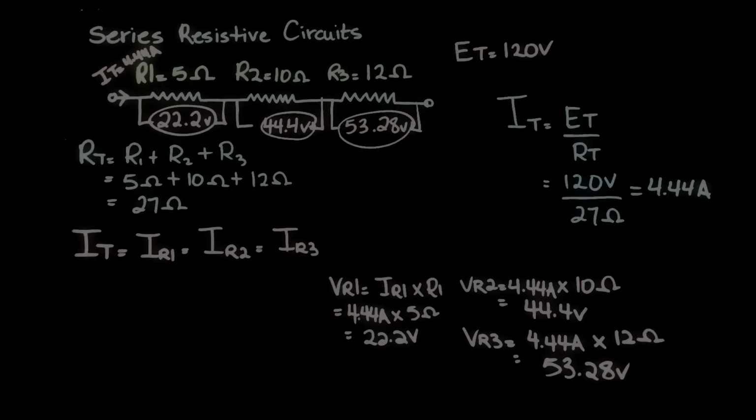And that leads me to the last law that's applicable to the circuit. So Kirchhoff's voltage law is true in a series resistive circuit. Kirchhoff's voltage law states that the volt drops equal the applied voltage or volt rise.